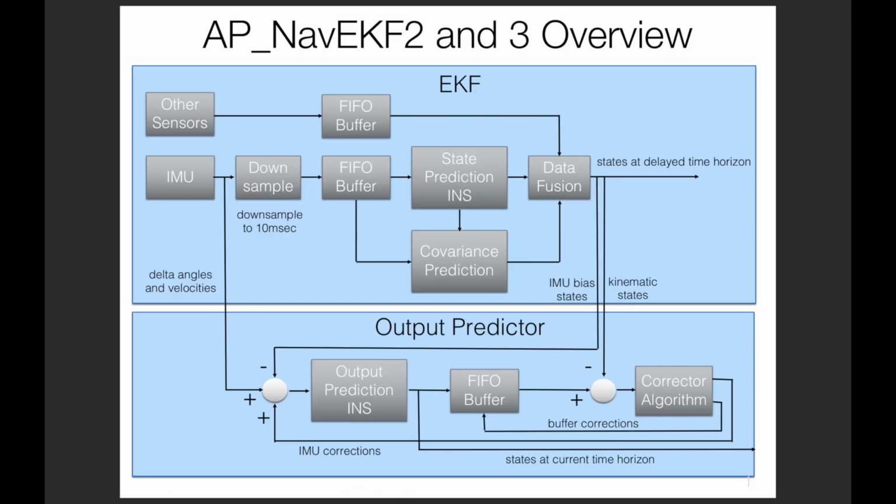Double precision. Double precision enables us to go tightly coupled with EKF, and it would improve the stability of the covariance matrix. So it's a good thing. Yeah. But the question is, any solution we do has to work on both boards, until we end up with a variant of the EKF that only runs on an S7 or an H7 board. So we're talking about an EKF4.